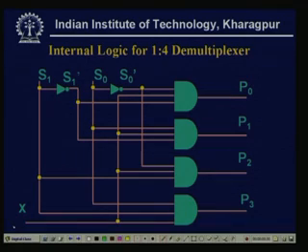So, if we define the operation, here for the n select lines only one input line will be there and there will be several output lines, and application of a specific control bit word to the select lines will direct the input to a particular output. So, this is the reverse operation of the multiplexer, and that is why it is called a demultiplexer.